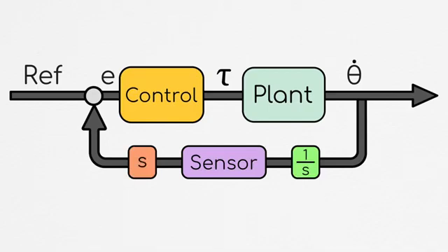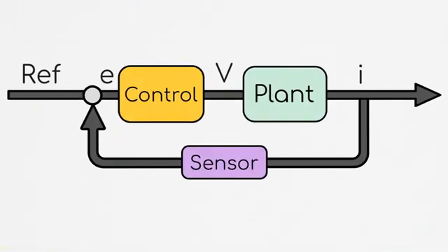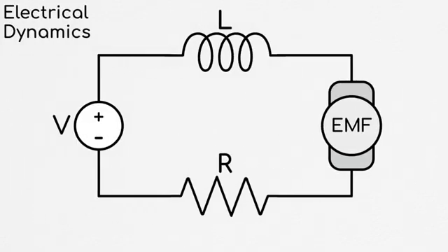But, as we talked about several episodes ago, we still have an issue. We don't have a way of directly dictating our motor's torque application. Instead, we're going to have to make a nested control loop which uses a value we can control, voltage duty cycle, to drive the current running through the system and thus control the torque. To design this controller, we're going to want to repeat our analysis from earlier, this time looking at the motor's electrical dynamics from a controls theory perspective.